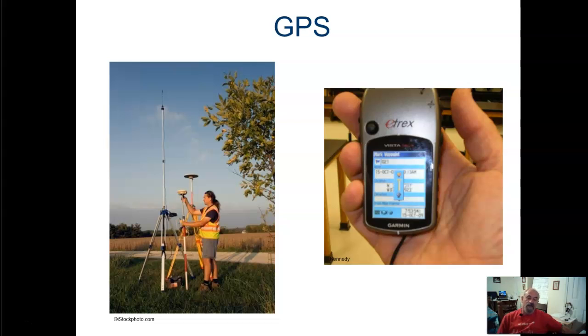The accuracy varies within the unit. The professional grade GPS surveying equipment, like that shown in the left image, provides a much higher level of accuracy than the lower cost recreational units. It calculates both horizontal and vertical positions to a high degree of accuracy. This surveyor is setting up GPS surveying equipment, which includes an antenna, a GPS receiver, and a remote receiver.